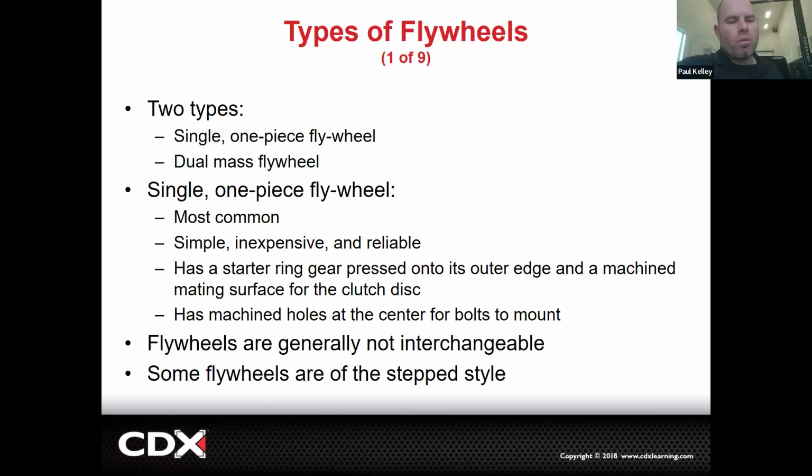Now we were talking about what the flywheel does, how it smooths out those power pulses. When you see this dual mass flywheel in I think about 2 slides, you'll be like, oh, that's going to make it feel so much smoother. It's going to be so nice and cushy on the driveline, and that's true. But it's going to cost 5 times the price.